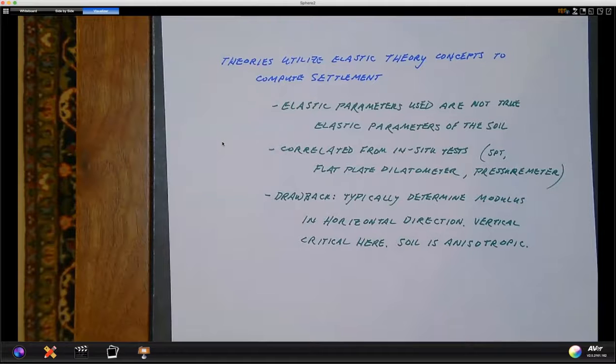And we'll call it that the results that will be evident from such an analysis are fine. They're of reasonable accuracy to work with and move forward for design purposes, but we are not modeling rolling and sliding of particles. That gets into all kinds of mathematics that's well beyond the call of duty for trying to assess settlements for regular type foundation design.